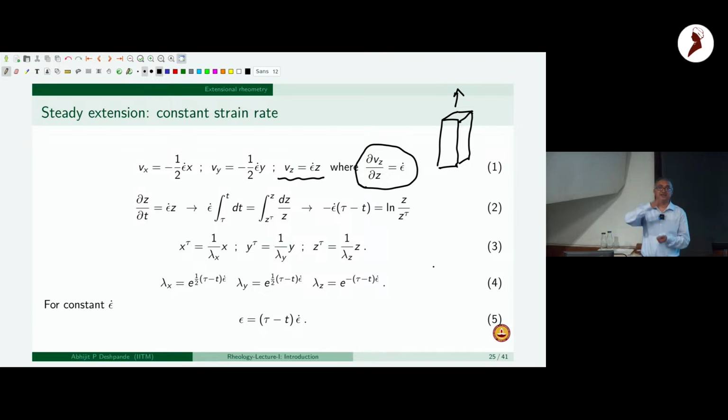That's how we achieve a constant rate. This is very similar to what we were doing when we were shearing at a constant shear rate gamma dot. Now we are stretching at a constant rate, and to do that, you have an exponential change in z. That's the exponential stretching I was talking about.